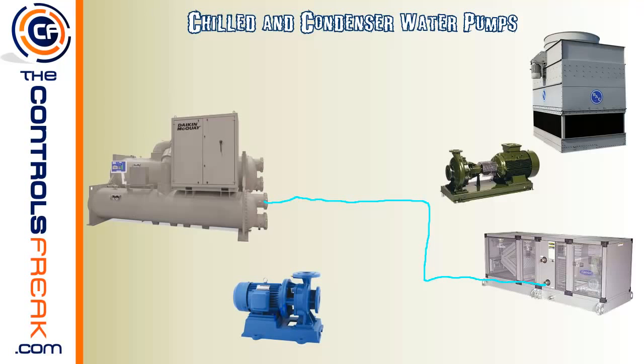of the coil. And the reason why is you want this to fill up with water before trying to pull it out. It's possible that if you were to supply this coil with water coming into the coil from this direction, the water may not actually fill the coil and you'll get air in this coil, which would mean that you're not going to get cooling on the upper portions of this coil if there was just air there, and water would flow in and then come down and get sucked out the bottom. So the reason why they fill it up from the bottom is that way you make sure you pressurize the coil and get all the air out of that coil. Alright, so we've got the chilled water coming in at the bottom of the coil.